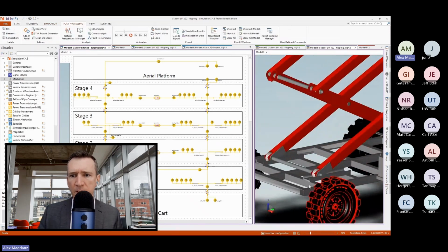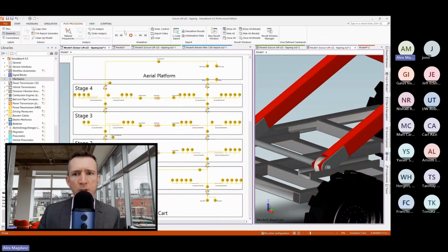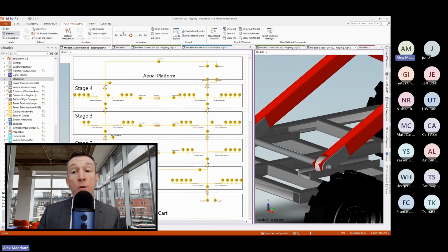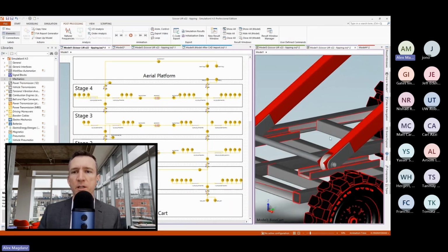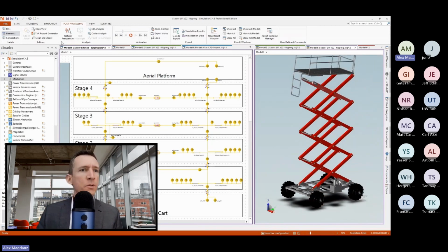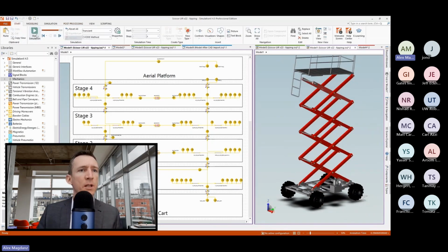we are missing, for instance, down here, our contact surface. If we continue simulating, you can see it just falls right through. So we need to add into the model the contact surfaces, both on the base card as well as the aerial platform. So I'm going to copy in those now as well. Let's reset our simulation here.